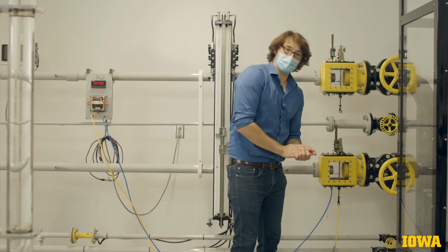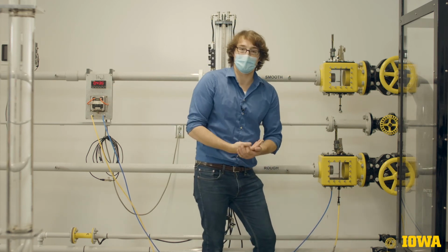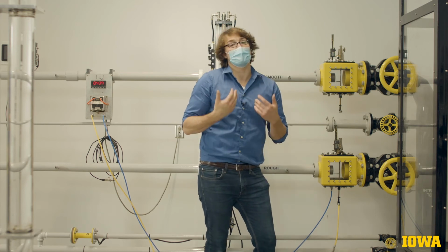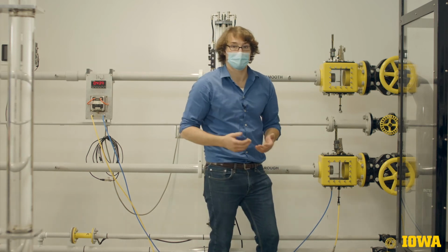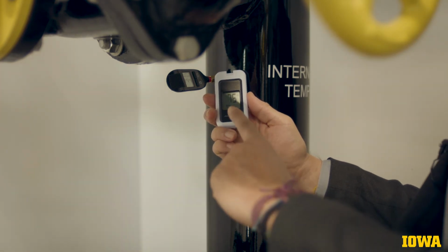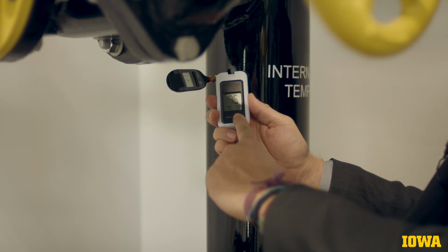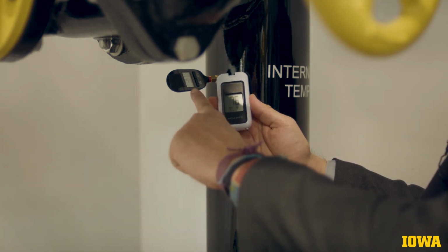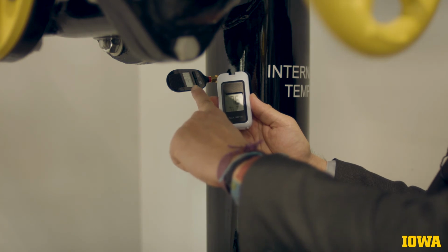As with the smooth pipe, we'll then conduct 10 repeated measurements with the probe located at 24 millimeters from center line to assess our precision limit. So this is our third measurement of temperature. As you can see, the temperature in the room has not changed. And now the temperature of the air moving into the system is 31.7 degrees centigrade.